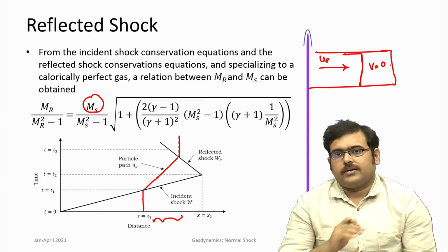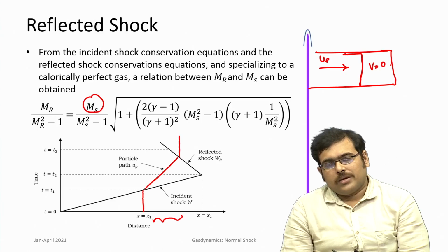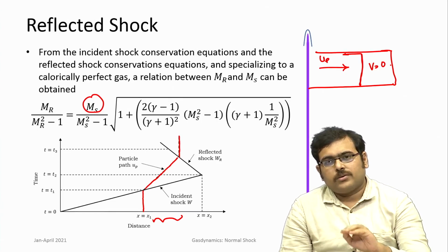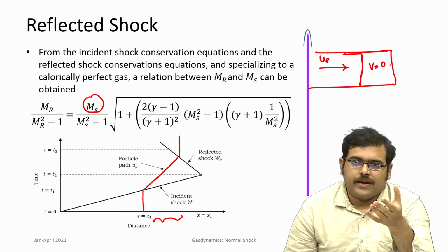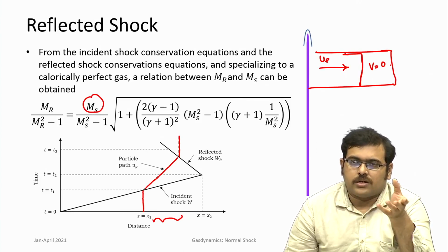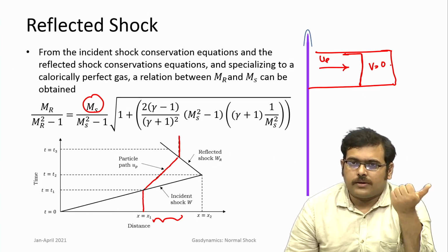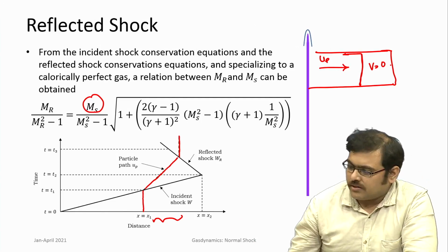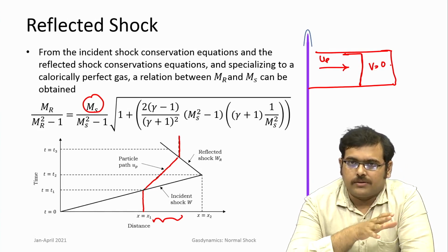So, the key idea introduced in this analysis of moving shock waves is that to analyze moving shock waves, all one has to do is sit on the shock and look at the motion of air relative to the shock wave. That makes the system of equations same as that of the stationary shock. So, the analysis of flow properties, static properties across the moving shock is the same as that of the stationary shock, but always make sure that you do the correct transformation.